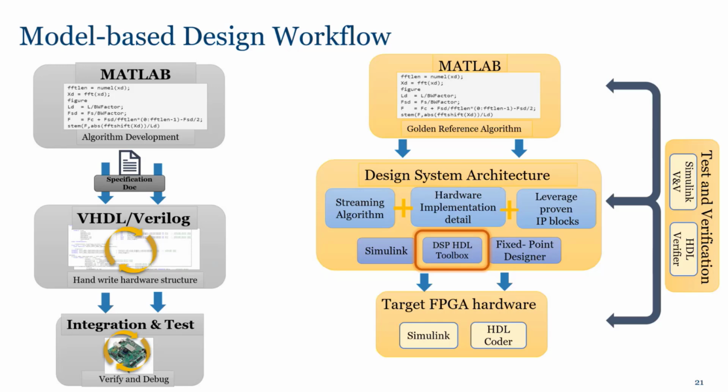All of that, of course, we can also use the continuous testing and verification that we have, and we can privilege the back-to-back testing between the golden reference and the design in Simulink, and later on what we have in Simulink and what we could have after we generated the code and implemented it on the hardware. So we keep the same concept of model-based design, but we are adding a very application-based layer, which is the digital signal processing HDL toolbox that we have here.